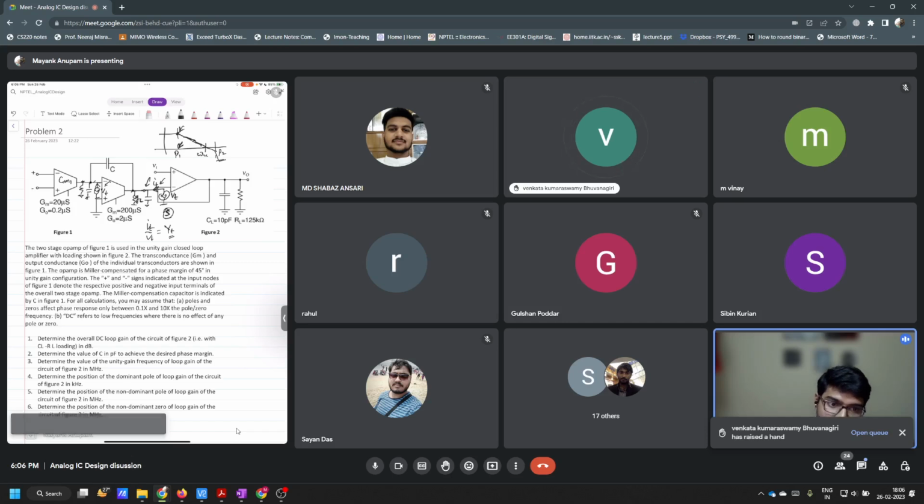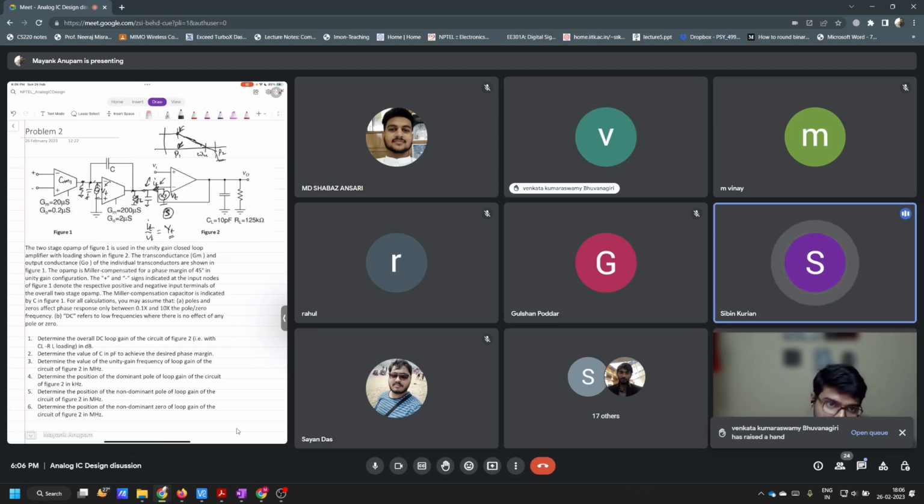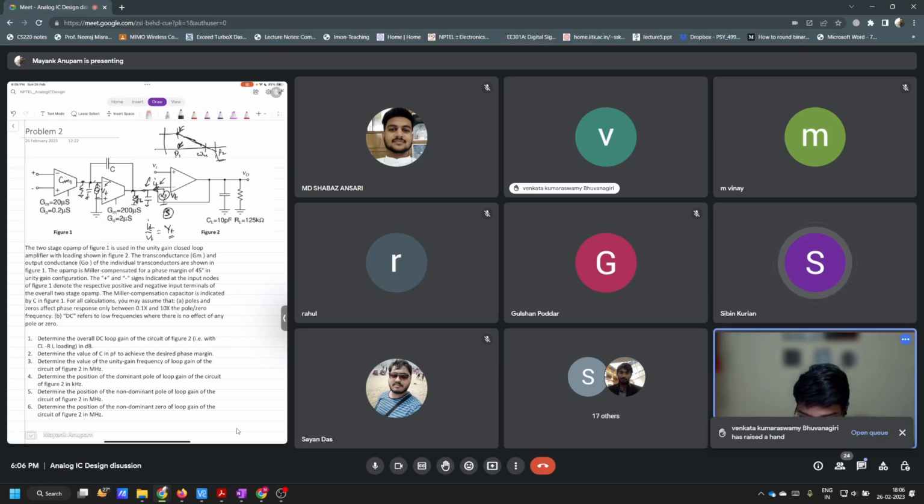And what does the imaginary component in admittance mean? It is basically due to the capacitor, capacitance. So you see what is the value of that capacitance and what is the value of the real term. That will correspond to a conductance or a resistor. And you find out what the pole location is because of that. So you will get some interesting ideas or intuitions.